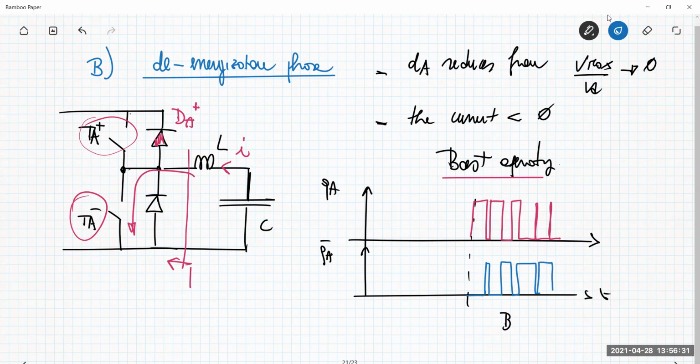Even here, you can say that since the transistor does not conduct the current, especially if it is an IGBT, for example, then I can also consider to maintain this transistor always off. An alternative approach is to consider this transistor always 0. So the Qa is always 0. Of course, this kind of reasoning will be dictated by power consideration and dissipation. You have to consider which is the best solution for your overall power dissipation.